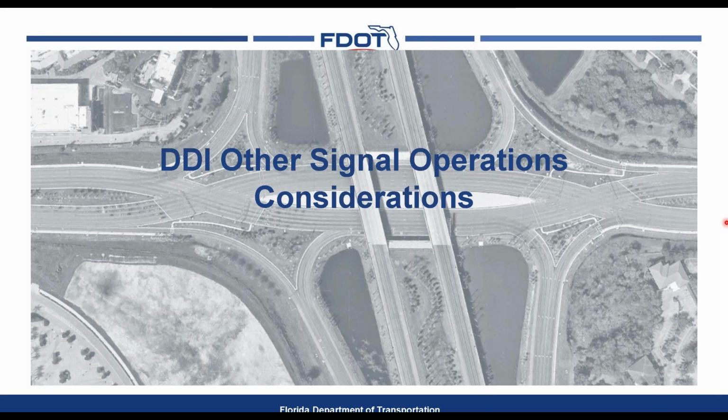We've got another question here, and then we can move on. At some interchanges, the off-ramp connects to a frontage road where through movements are permitted. Can a DDI operate in such a condition? So Randy, I think this is building off of the statement I made in answering one of the questions, that a through movement from the ramp through the intersection is not available on a DDI. Again, that's what keeps it a two-phase signal. Whereas on a traditional diamond, the traffic can get off the freeway, go straight through the arterial, and get back on the freeway.